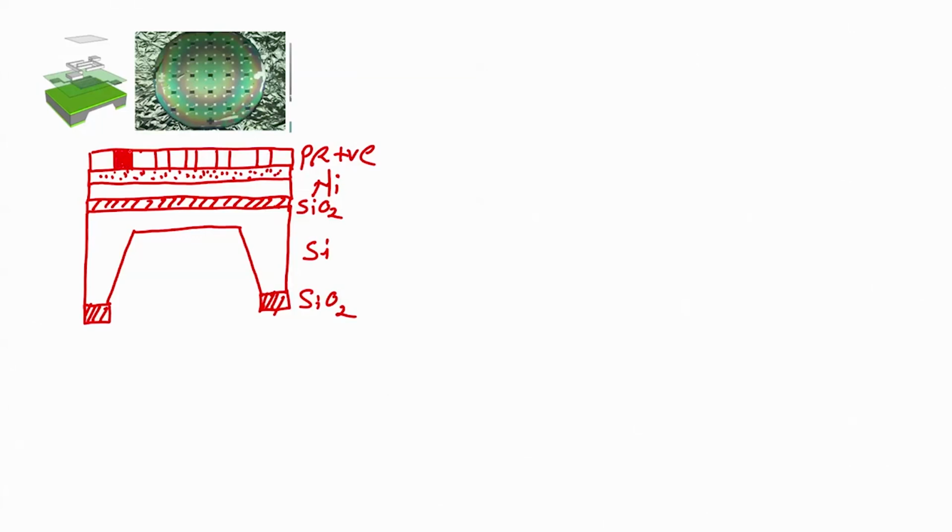So, for having a heater, we have to load the mask. For the heater, after depositing nickel, we need to fabricate a heater. We have to pattern nickel to fabricate a heater. For fabrication of the heater, we have deposited photoresist and then we have loaded a mask,